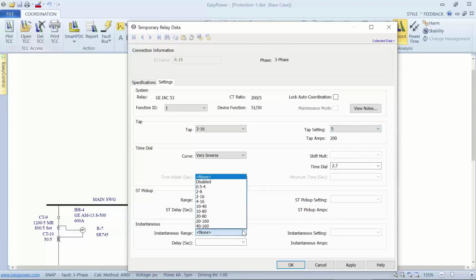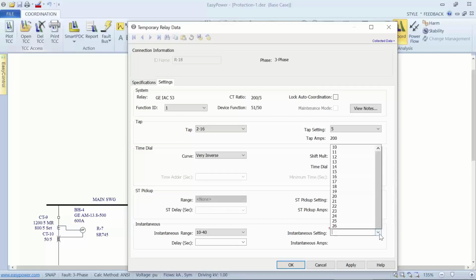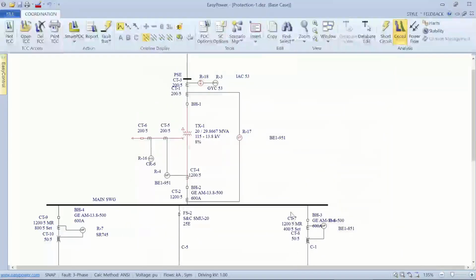And we're ready to set an instantaneous trip of 1400. Pretty close. Looks like it's going to be about 35. All right, so with that, now we have the relay set for protection of any current detected on the primary side of the transformer.